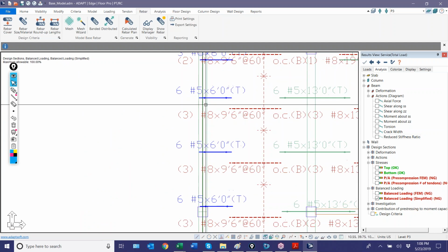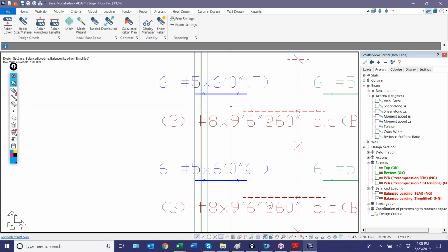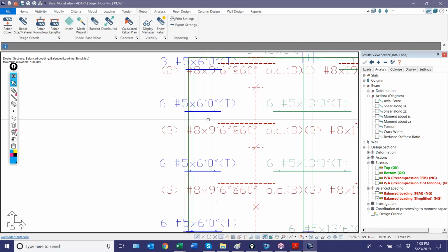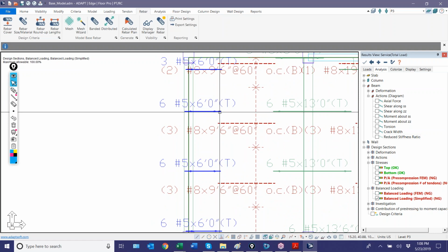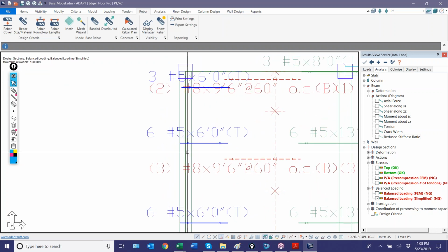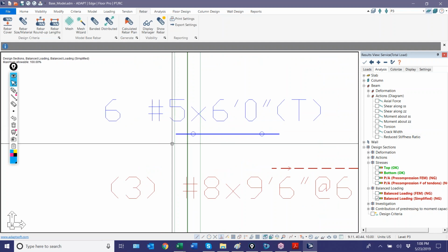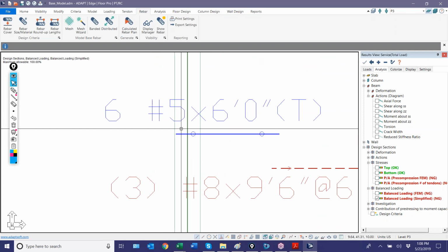The blue rebar, the color trigger actually comes from whenever a bar extends into two different thicknesses. If the start point and the end point of the bar are located in two different elements with different thickness, then this will trigger blue. It's really just a warning to the user for detailing. So here you can see all of these bars on the perimeter actually go out, and they get extended outside of the slab because of some bar extension rules that we're using.